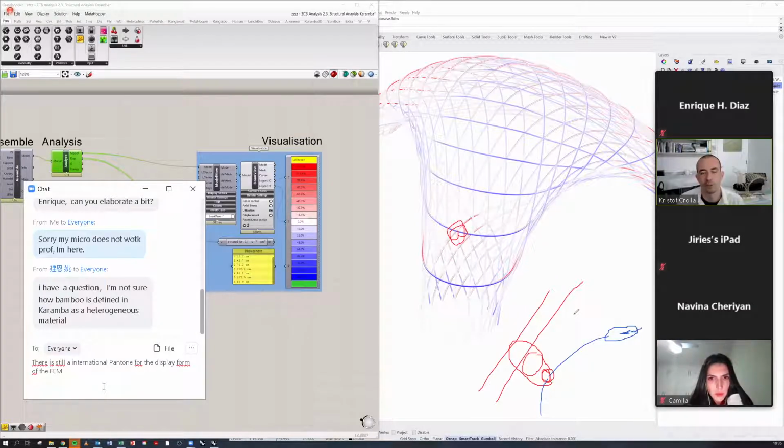But the challenge is, how do you go about it? Because the minute you start to pre-tension one, you're deforming your bubble. So you have to very gradually first install all of them without tension, then a little bit of tension everywhere, and a little bit of tension everywhere, and constantly be aware of the behavior of the structure that you have. But steel cables could work very well. Bamboo in principle as well, because that can take compression and tension.